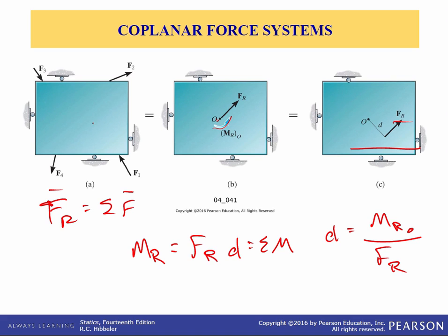You see what we did here? We sum forces about some point O, and we have the resultant force acting at that point O with an applied couple, applied moment rather, due to all these forces here. This is also equivalent to moving that resultant force vector some perpendicular distance d away, such that F_r times d is equal to the original moment calculated in the original system.